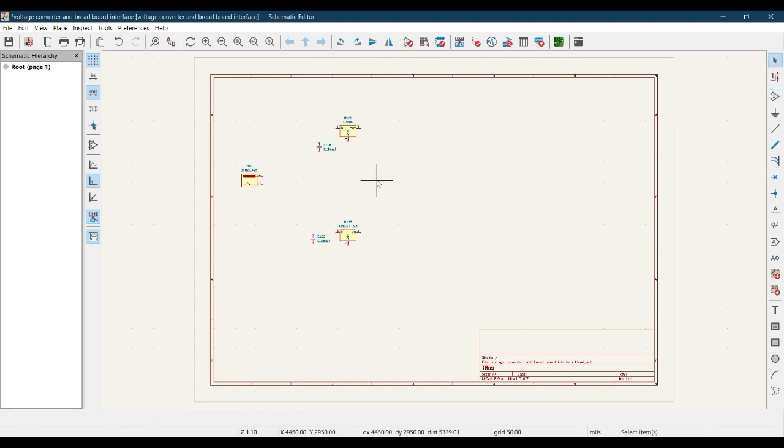The other way is, I don't want to click on add symbol, search and add again into the sheet. The simplest way, if you once have placed the symbol, highlight the symbol, hit Ctrl C and Ctrl V, and the symbol is copied, and again click on the sheet, the symbol is added into your drawing sheet. Again Ctrl V, another symbol is added here.